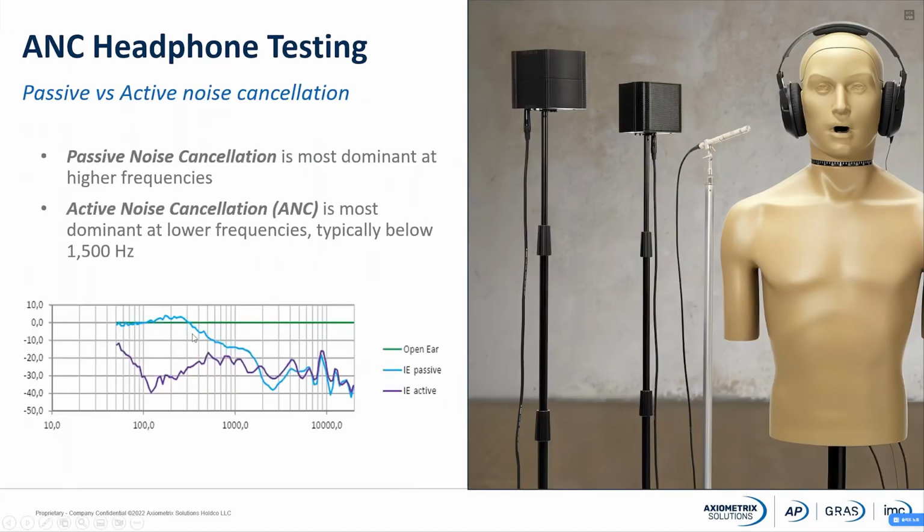The green curve, it was basically comparing the open ear situation to itself. So I was measuring the open ear situation, yes, and then I was adding a compare derived result within the APx software, comparing that curve to itself. So I get this reference flat curve in the system.